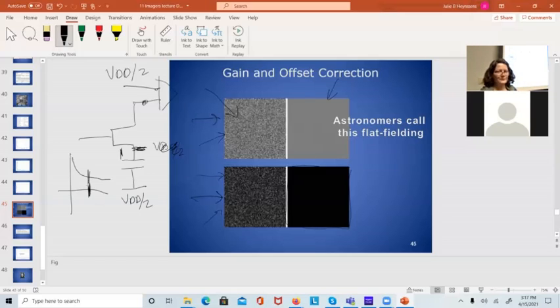Okay. So, any other questions? Why wouldn't we just use read-only memory or some sort of puff to say this chip is unique and it is chip number 123? Okay, so they've got things like that. They have serial codes that are associated with motherboards, and they have encryption keys that are stored in hard memory that stays there when it powers down, non-volatile memory. But the problem is people can read those off of the memory because they're there all the time.